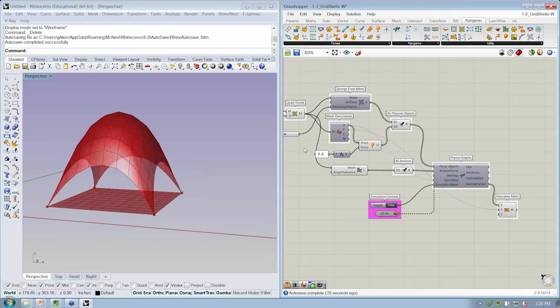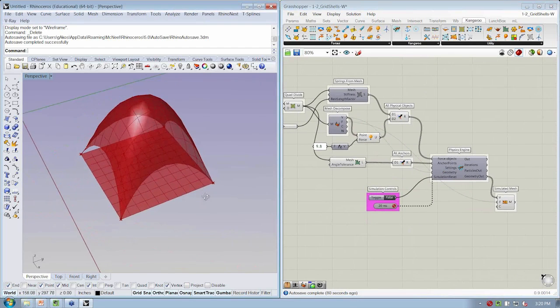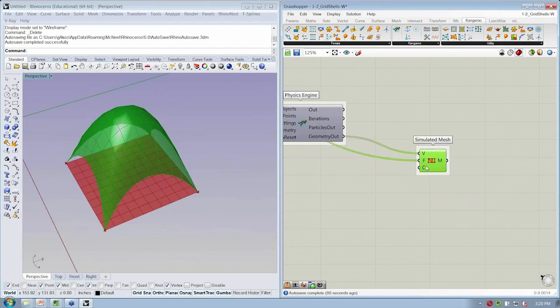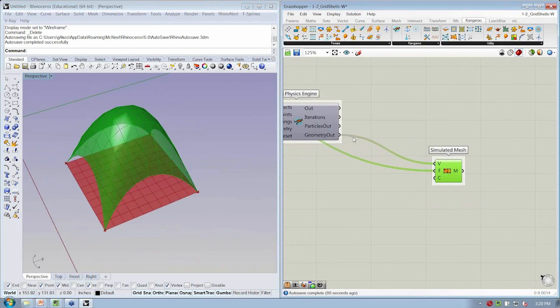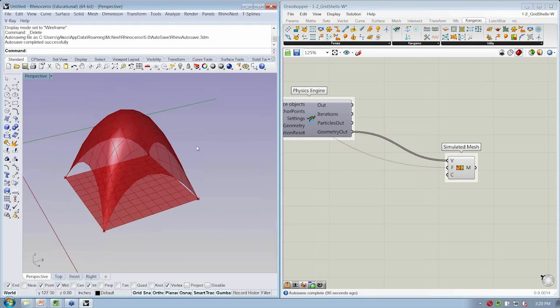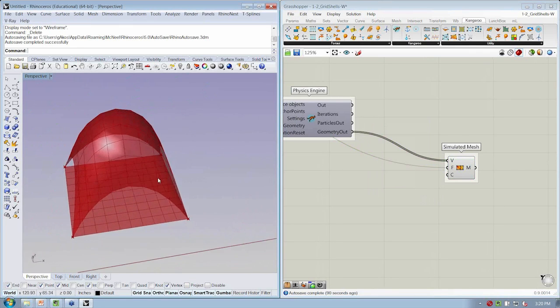All right, so whenever I'm doing much of anything in my Grasshopper file and I'm working with a simulation, I want to make sure that I block my timers so that it's not trying to calculate over and over again in the background. All right, what we're going to do is go to the geometry out area of the file after the physics engine, and we're going to start to develop a little bit of logic to color this shape based on a certain kind of analysis, right?